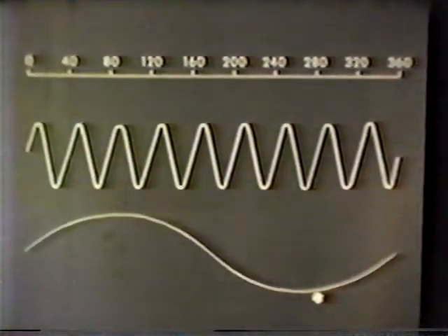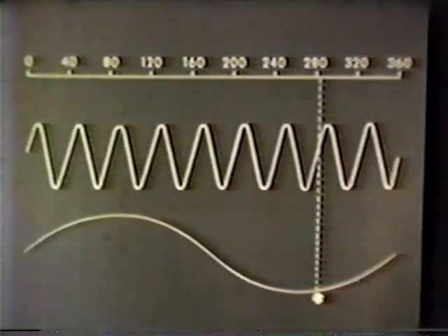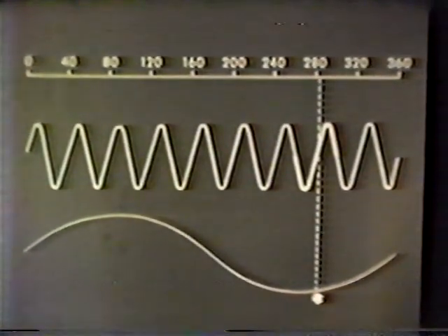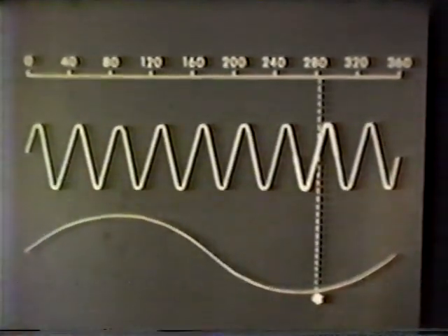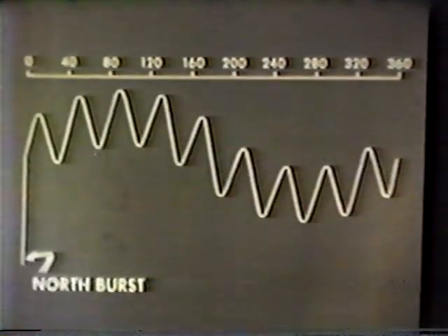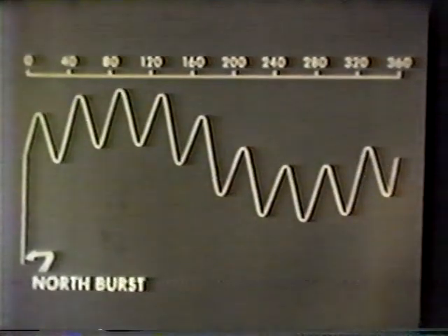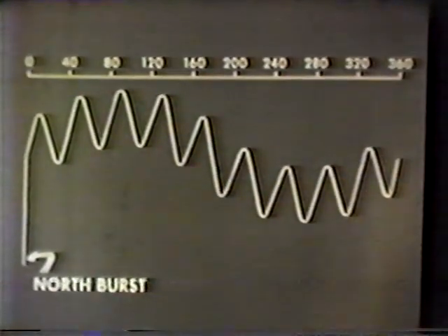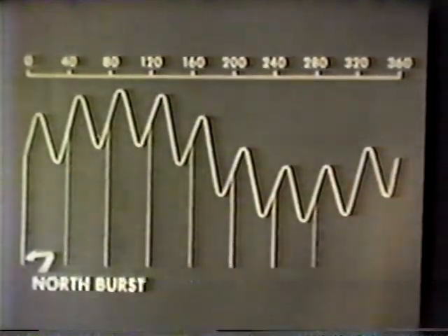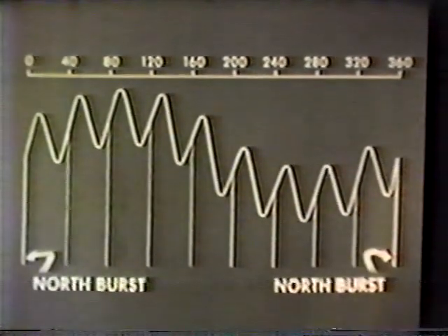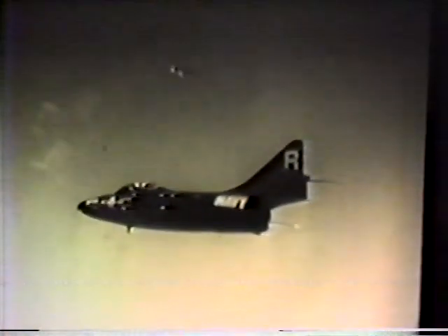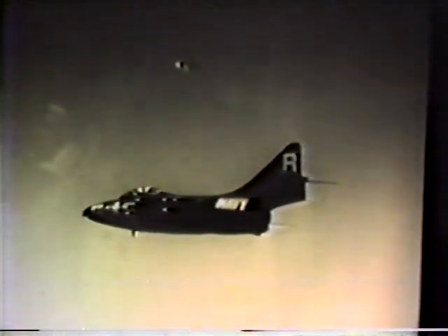Thus, the 15-cycle modulation is necessary to find approximate bearing and indicate which of the 9 cycles of the 135-cycle modulation is applicable. One reference burst doesn't allow an aircraft's equipment to check bearing often enough. So in actual practice, a beacon transmits auxiliary reference bursts every 40 degrees of antenna rotation after transmitting the fundamental burst. Now let's watch Tacan in action again, in more detail.